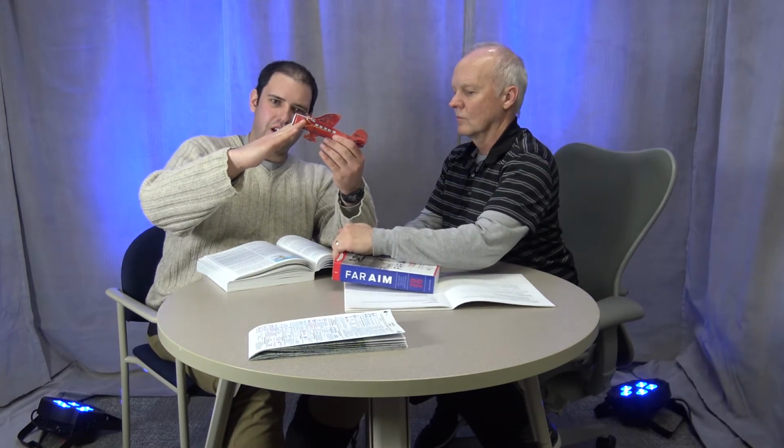Now, you'll also notice as we climb out, you'll have to add more right rudder. That's partly because as the airplane has an angle of attack, the propeller is spinning, but the propeller is not perfectly perpendicular to the relative wind. It's on kind of an angle. So as this blade on the right side comes down, the relative wind is sort of coming up, right?